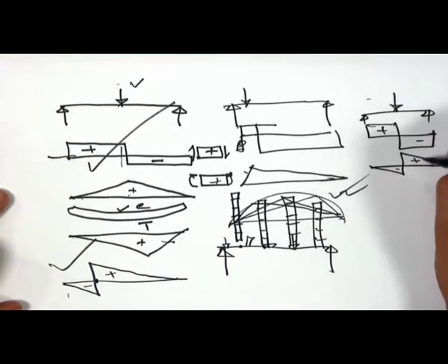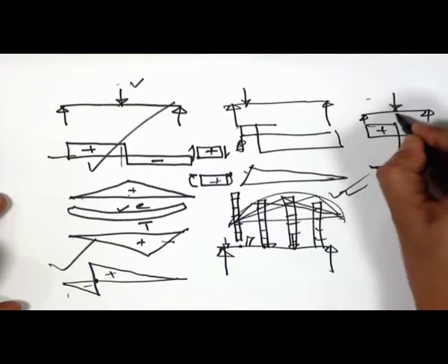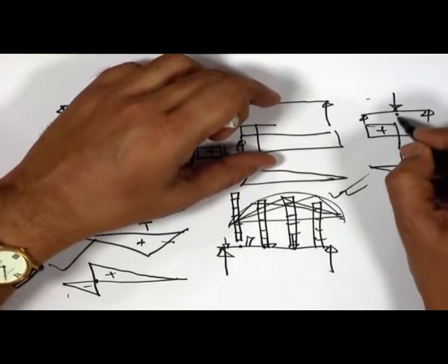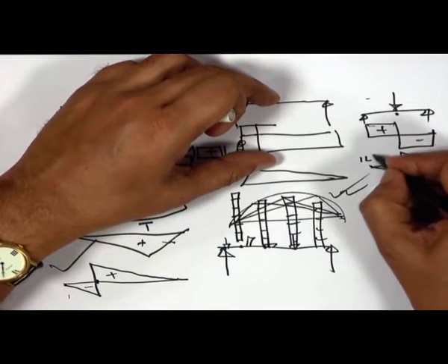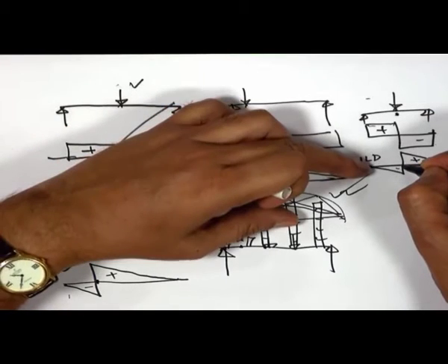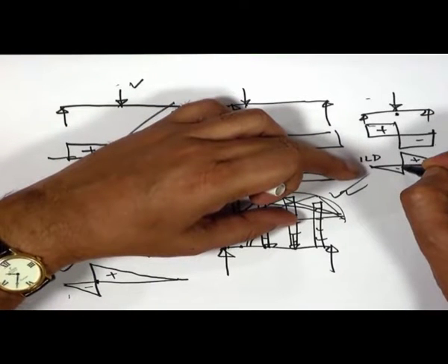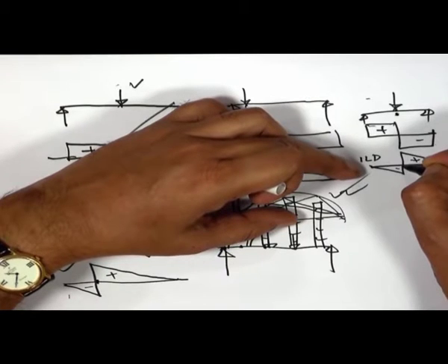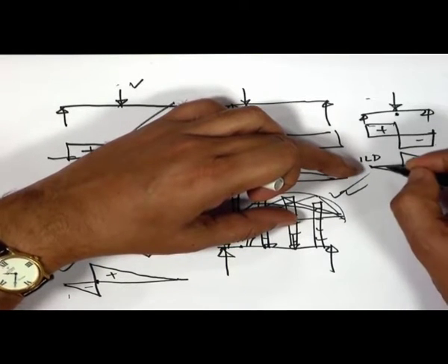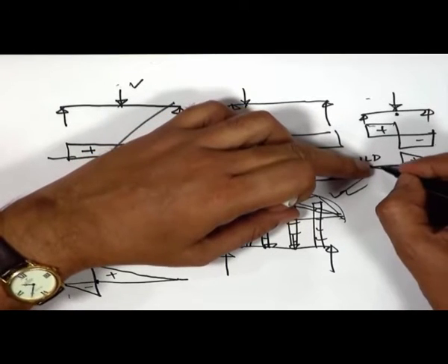Now it is very difficult to digest, because what I am doing is sitting here; this shear force diagram is completed. For the influence line diagram, I am sitting here and observing how the shear force is changing there as the load moves in space.